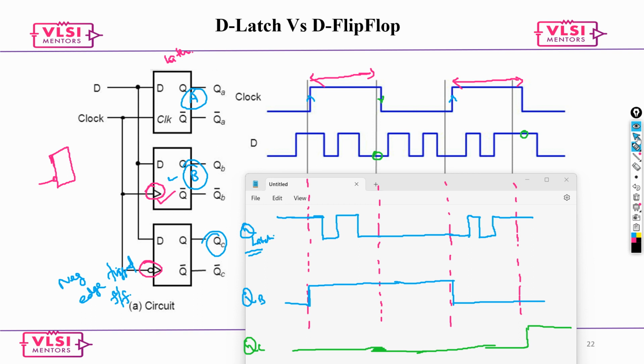First, a latch is generally level triggered. Wait, it is not level triggered, it is level sensitive. Yeah, level sensitive, sorry. For a positive latch, we want to follow at the positive level, the same data will be obtained. At the negative level, it will not be obtained for a positive latch. Vice versa for a negative latch.